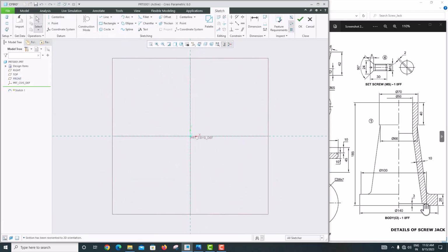Now we just want to draw this hatched portion only. We'll be revolving based on this axis. So I'm just creating an axis using geometric datum center line. Then I just want to create a line one by one. First I'm just creating a small line.